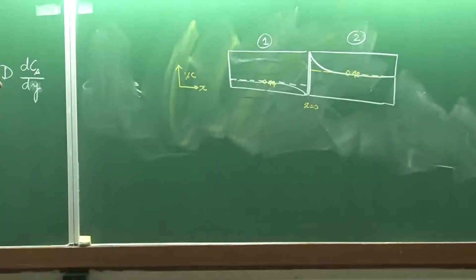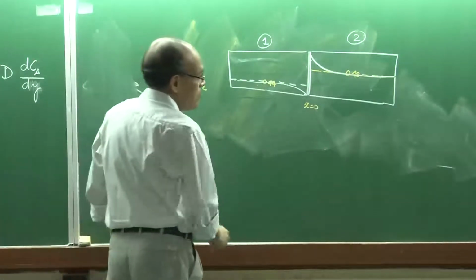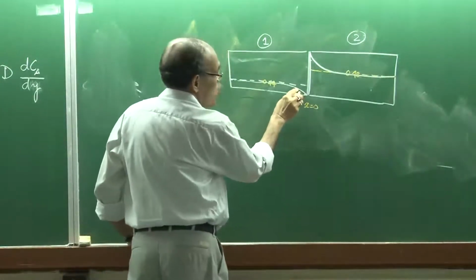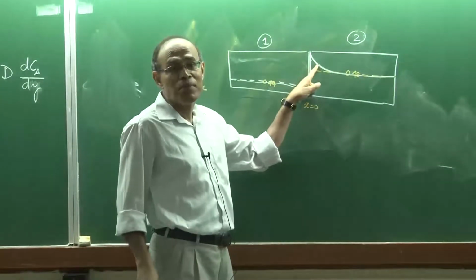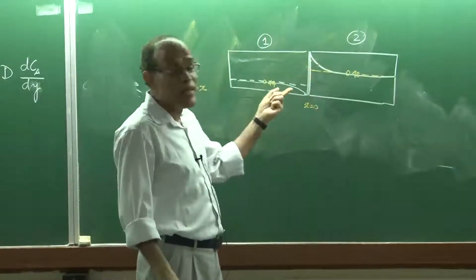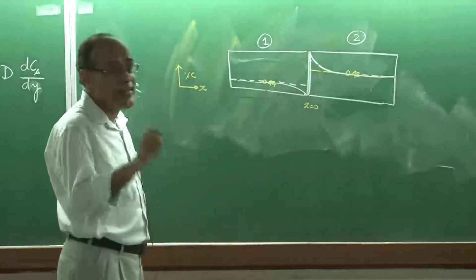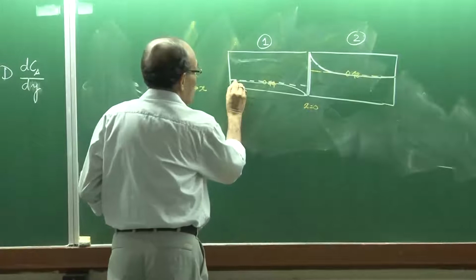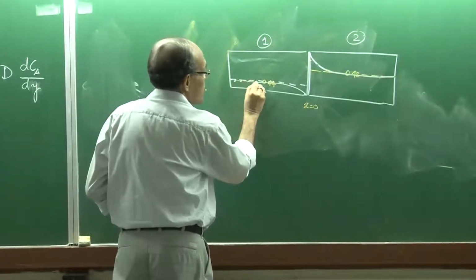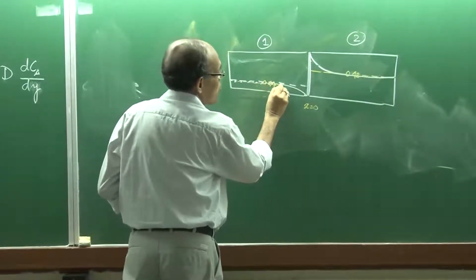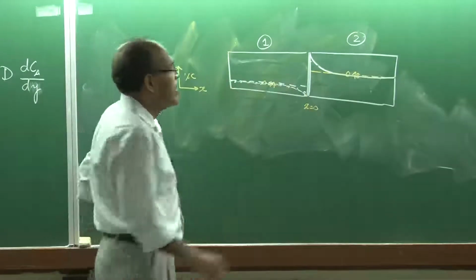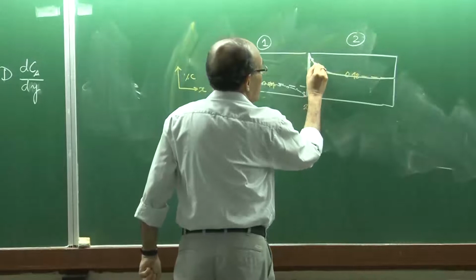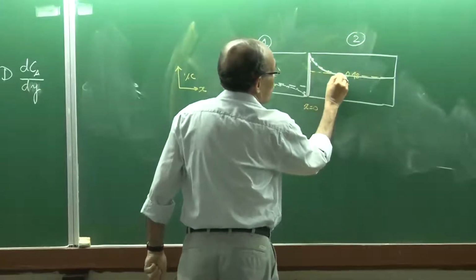What does this indicate? The solid lines that I have drawn here are the concentration profiles of carbon after a span of 13 days. That is what Darken found out, and these are all based on his discrete carbon composition measurements. The uniform concentration was horizontal, as the line indicated, and then by taking samples, these concentrations were found.